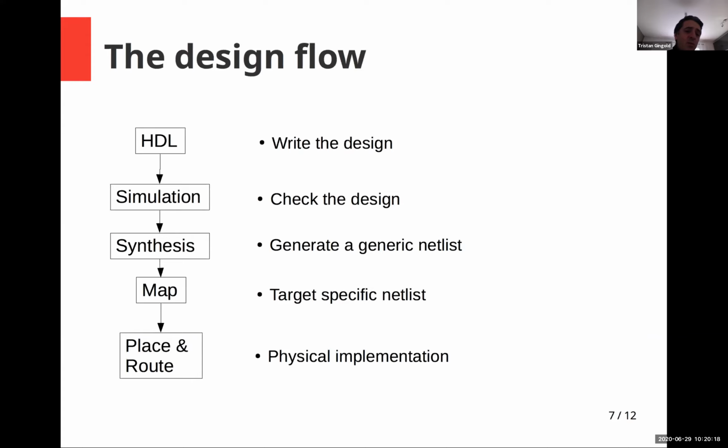And synthesis is a process by which an HDL description is transformed into a netlist. In addition to simulation, you can also do some formal verification, but usually formal verification uses the output of synthesis because it needs to have very low-level knowledge of gates and memorizing elements.